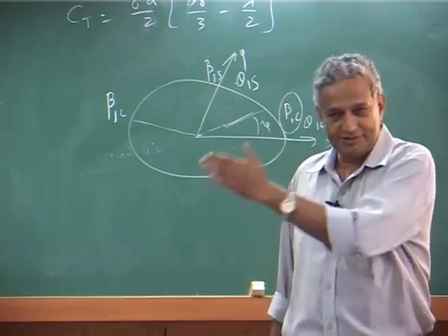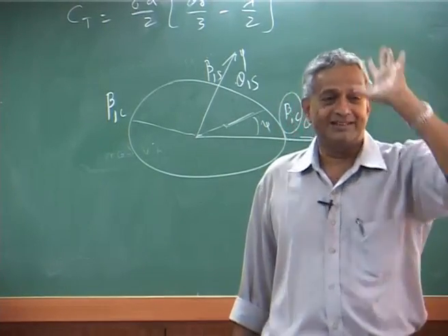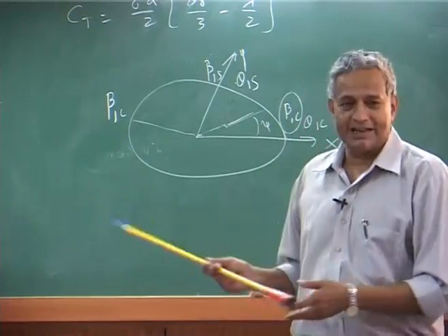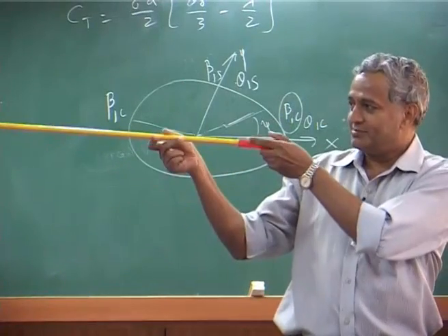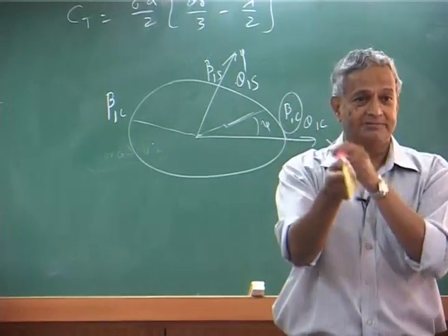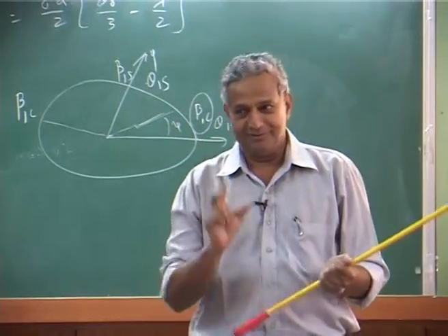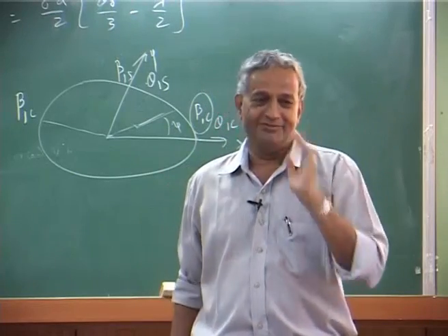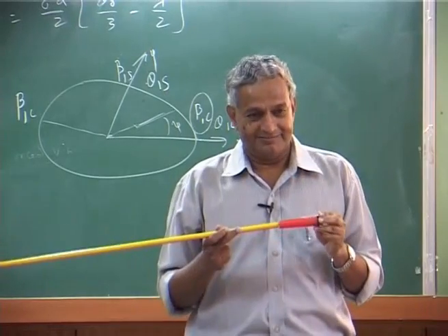That means, if you give an input now, its effect will be shown after 90 degree, then you convert it to time. Here we know that 90 degree is basically, in this disc, if I change my pitch angle here, the response will be here. That I can show in the lab when we rotate the blade, because you can see clearly only the stabilizer bar.